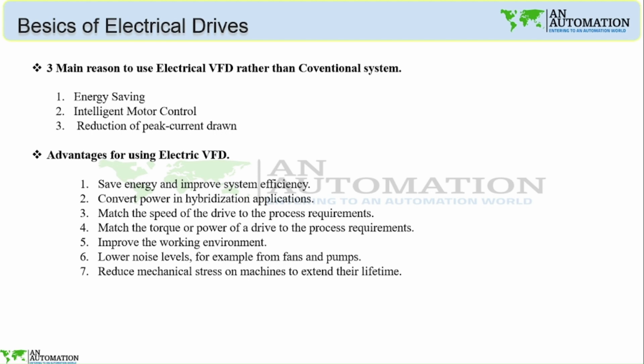When it takes enormous torque and enormous current, the current is directly proportional to the torque. So if the torque level is very high for an instantaneous time or a small time, then the machine or machine shaft will be directly damaged, because it takes enormous stress at a certain period of time. So it will damage the mechanical system by its mechanical stress.